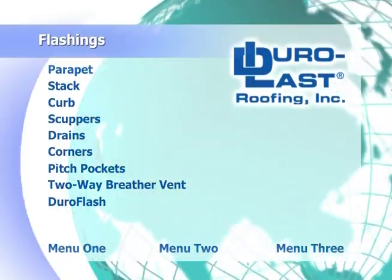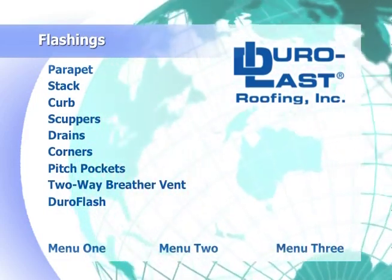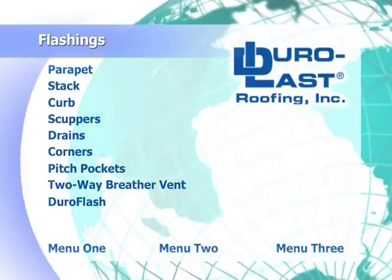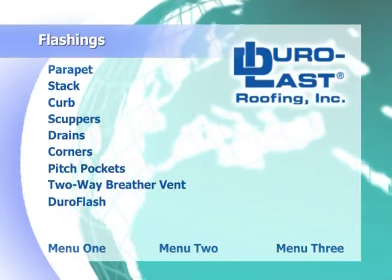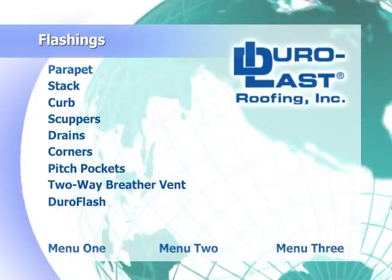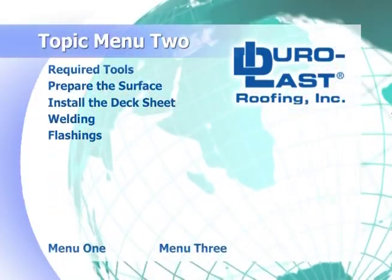As you are installing your deck sheet, continue to fasten the fastening tab right up to the wall. Fasten into the deck at the base of the wall and also into the wall just above the deck. Continue fastening this tab in the same fastening pattern as the rest of the deck sheet. Hand pullers can be helpful to pull the tabs as they are fastened.